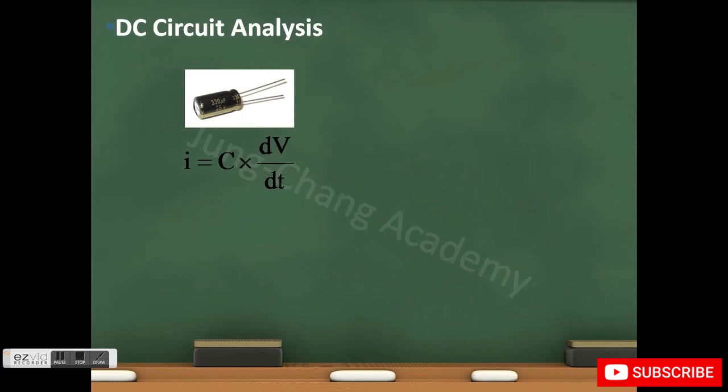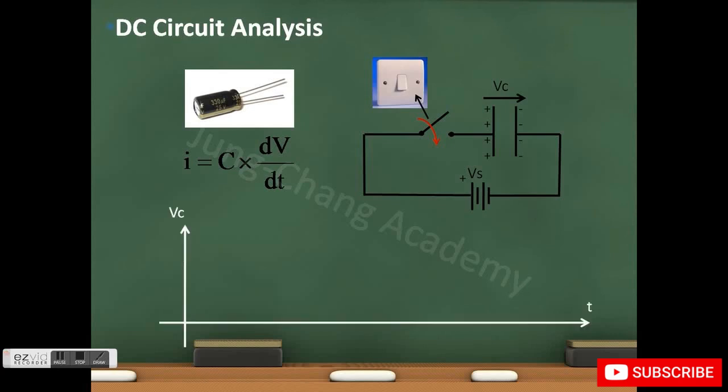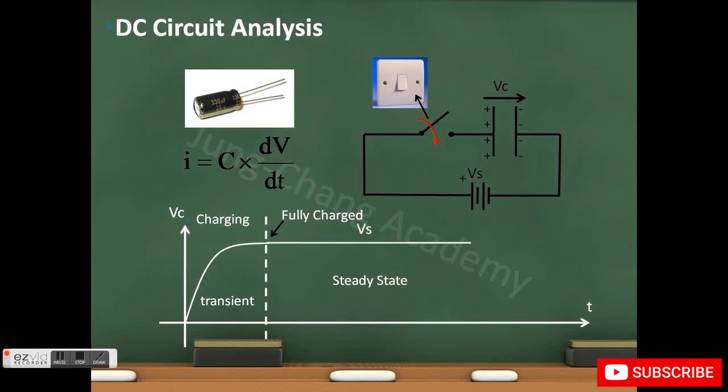Looking at the capacitor example, if we now introduce a switch to the circuit, at the instant when the switch is closed, the current starts to flow into the capacitor, and the two metal plates get equal but opposite charges, which leads to a potential difference Vc. As the current continues to flow, Vc increases until it's equal to the power supply voltage. At this point in time, the capacitor is fully charged, and no more current will flow in the circuit.